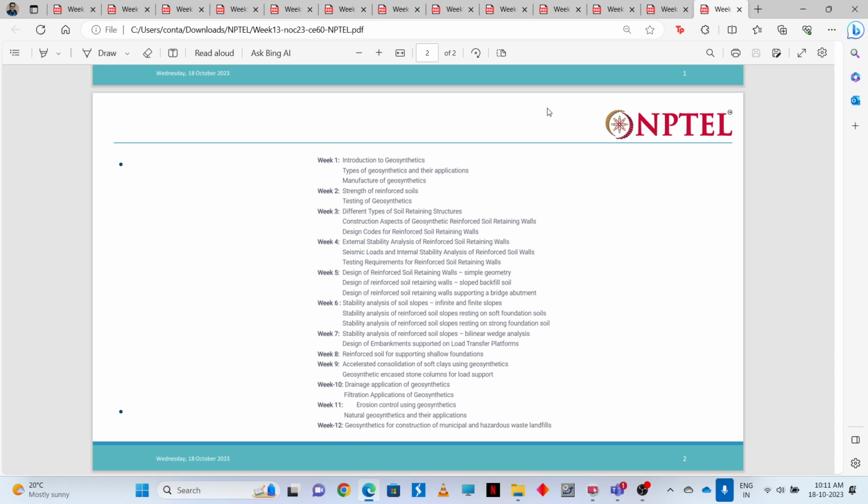Using these softwares, we can do these complicated calculations, how the pore water pressure changes when rainwater is flowing. These are dynamic problems, right? As rain falls, the pore water pressure is continuously changing, the soil gets wetted, there is loss of strength of soil. All these things we need to simulate properly. We cannot just simplify these things.